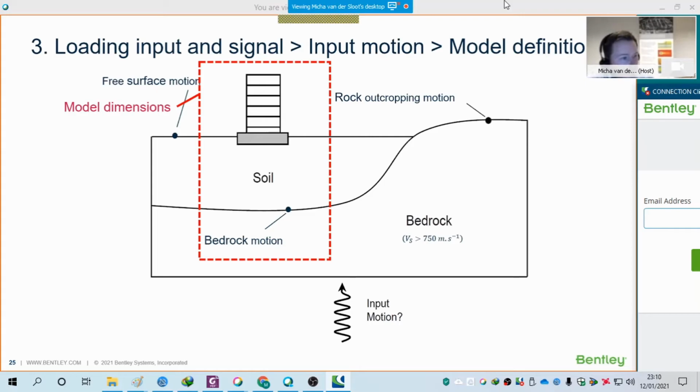Mike asked the question, is hardening soil suitable for dynamic analysis? If you're going to do dynamic analysis, I would use the HS small model, so the hardening soil with small strain. That model is more suitable because it takes into account the change from a high stiffness at the very small strains to a bit softer behavior when we have larger strains. So it has a stiffness degradation curve based on the shear strain. So with that, we can have proper hysteresis effect. So that helps.